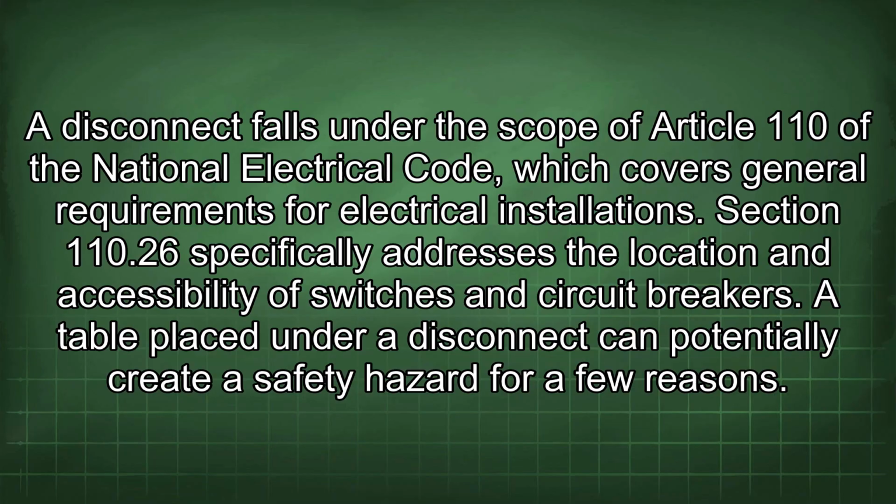A disconnect falls under the scope of Article 110 of the National Electrical Code, which covers general requirements for electrical installations. Section 110.26 specifically addresses the location and accessibility of switches and circuit breakers. A table placed under a disconnect can potentially create a safety hazard for a few reasons.